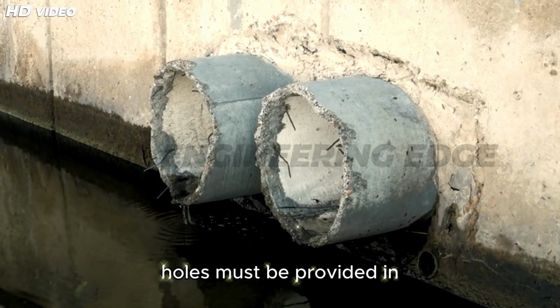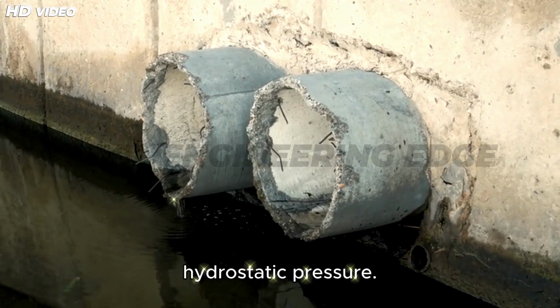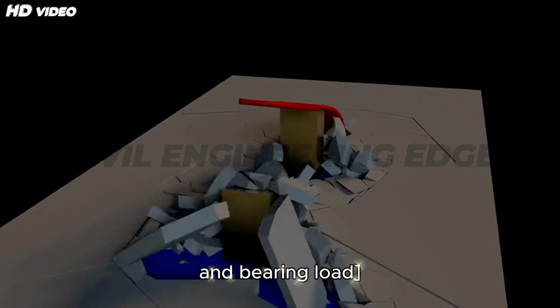Drainage pipes or weep holes must be provided in the heel zone to relieve hydrostatic pressure. Design of toe slab. Scene: animation showing toe slab resisting uplift and bearing load.